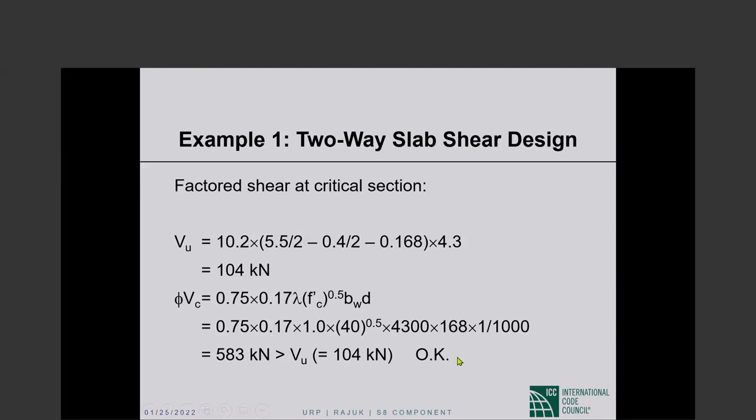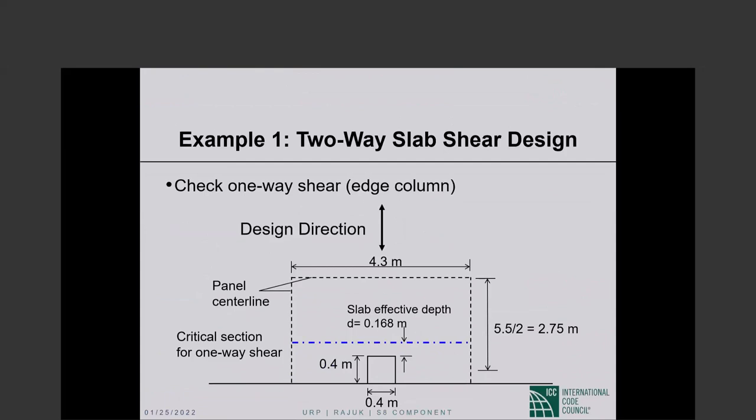So that is okay. I actually have never seen a one-way shear problem in a flat plate. We always check, but I have never seen any problem. Never. Okay. Now that was obviously at an interior column. Now we will check one-way shear at an edge column.